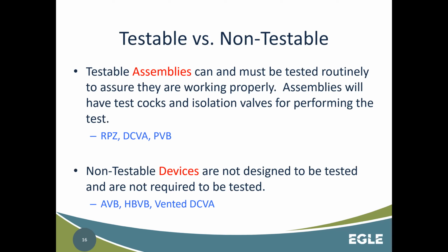Then there are non-testable devices. And the thing is, these are non-testable and they are used in the industry as reference as devices. All right. So assemblies are testable, devices are non-testable, meaning they don't have test ports. They're typically not mechanical in nature, but they have their drawbacks.